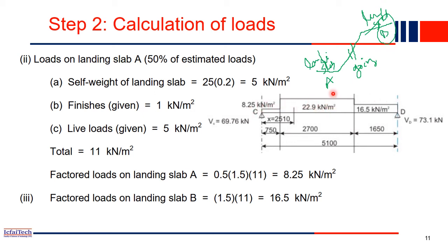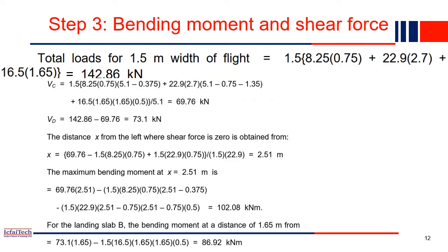So now it is essentially a very simple beam design with loads already computed. So now we have to draw the bending moment, find out what is the maximum bending moment, what is the maximum shear force, and the simple beam design will follow it. So now you can see how we have disintegrated the entire slab into a simple beam design with the different loading pattern. So how we idealized, that is very much important to understand. So now already we know the loads. Now we have to compute the maximum bending moment and maximum shear force coming into the beam.